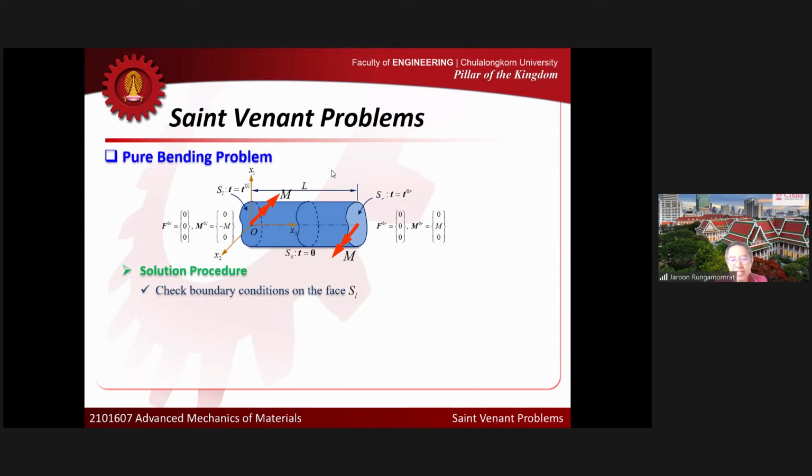At the left end, first I have to generate traction, and then use that traction to compute net force and moment. So I will use the expression that I used before. This is the expression for the net force in terms of the stress components that we guessed. We can plug in sigma 1,3, sigma 2,3, and sigma 3,3 into this equation, right? We know that sigma 1,3 and sigma 2,3 are 0 for the guessed form, so that term disappears and that term disappears.